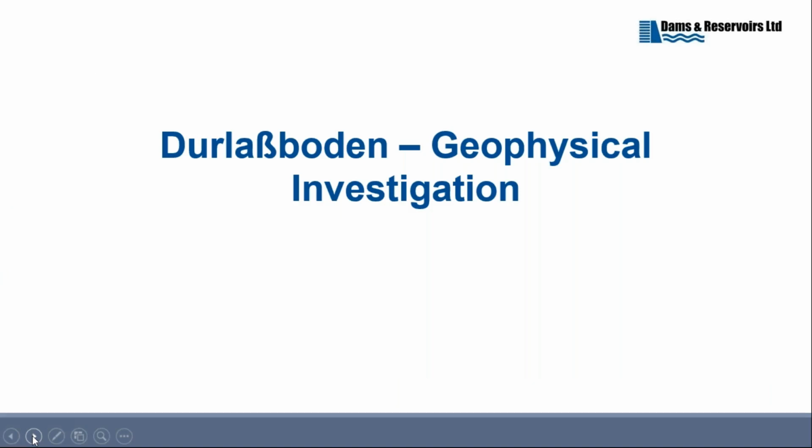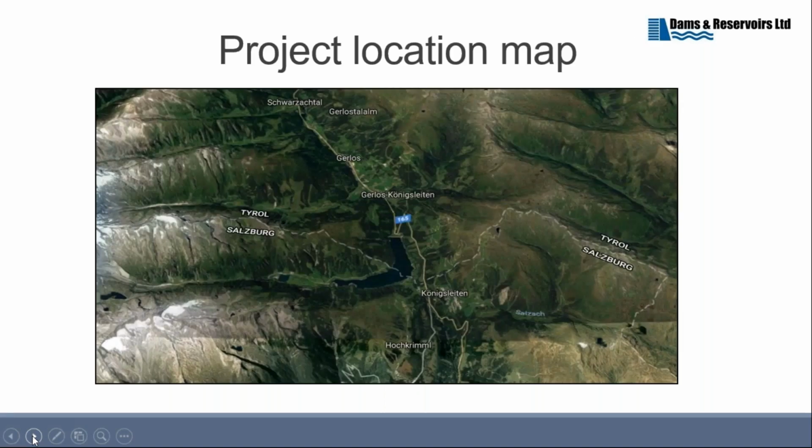You might buy out 1 or 2 houses if it's a small community, but when there are large communities around, then you certainly wouldn't contemplate moving people. So the only way to move it on that chart is either to try and find land, and you might be hemmed in by other bits of infrastructure, to put some sort of stabilizing berm or cutoff, or you have to just look at those levels of uncertainty.